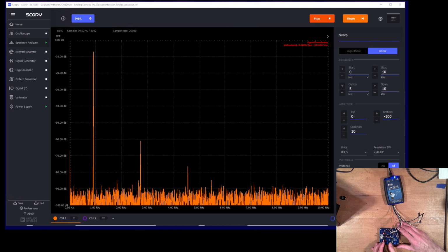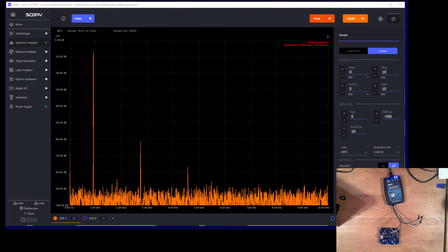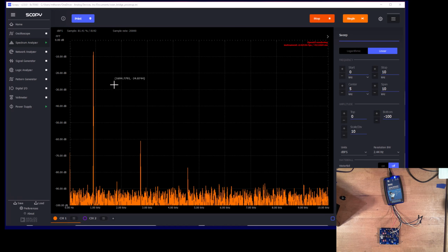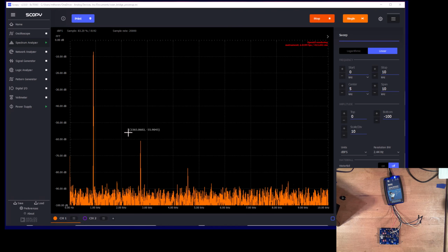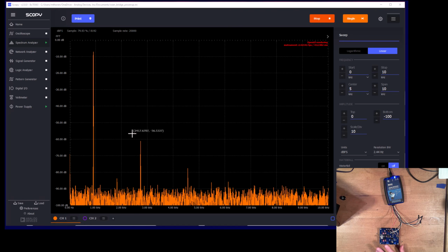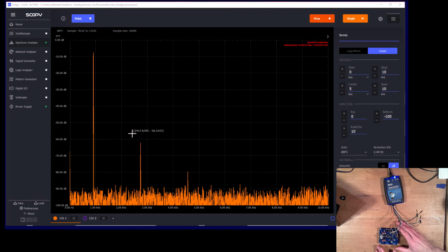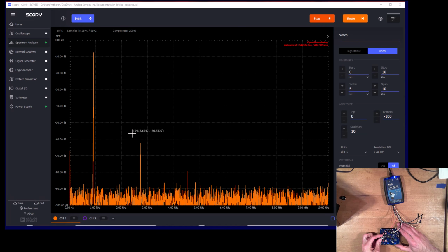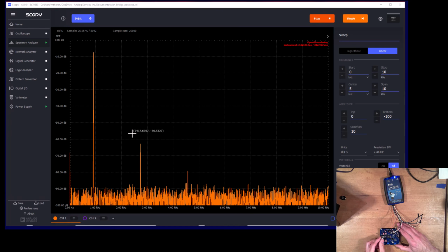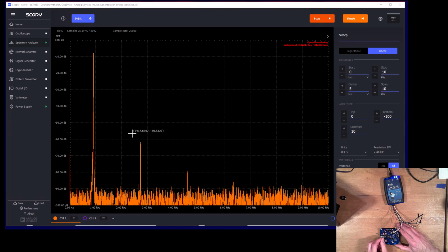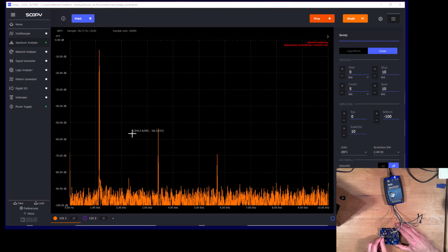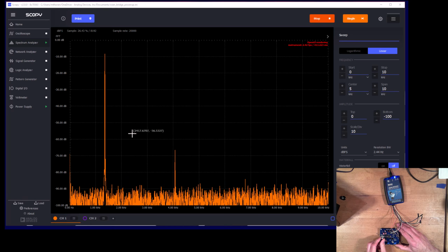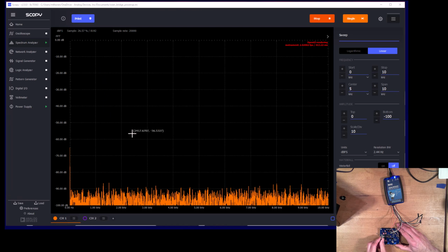So yes, I can get it to work, but if I want decent distortion, 10, 20, 30, 40, 50 dB distortion, I really have to work at it, and it's quite touchy. Furthermore, because of component imperfections and mismatch in the 2 stages of this dual potentiometer here, if I change the frequency, then I have to adjust the gain a little bit as well, right?